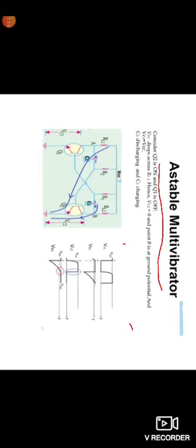Whenever VCC is applied, the switch is closed, and the current moves through, with the voltage drop across RL1 being VCC. Here VC2 is equal to 0. VC1 is the voltage across the transistor Q1. That means at the point A node, the voltage is VCC.